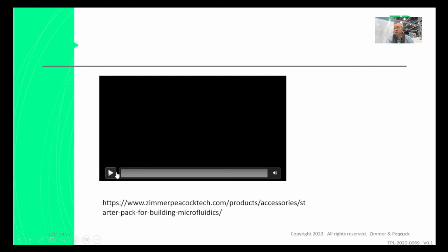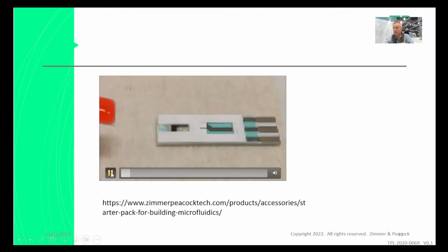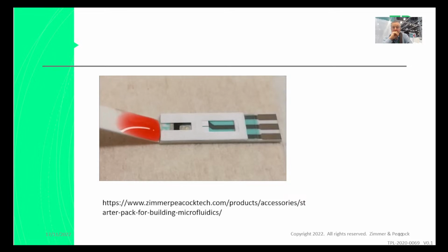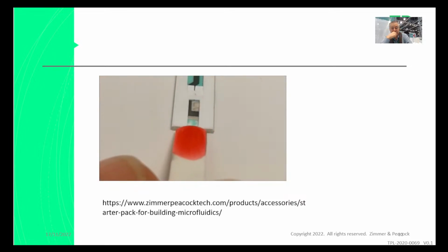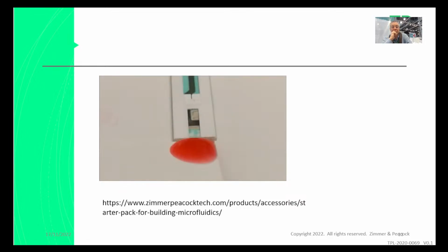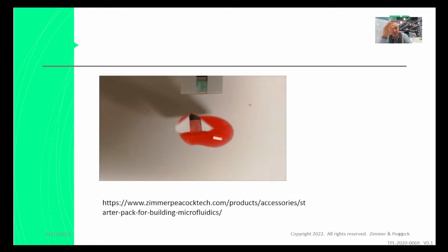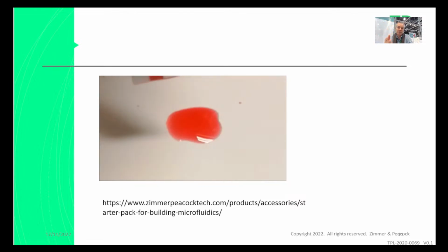Now that means you can construct devices like this. So you're not just pipetting the sample onto the sensors or electrodes, you're actually able to capillary fill the sample. You might notice there's something called an air hole. I'm reading the email from the inquirer, and they understand that you need this air hole, because otherwise these capillaries won't fill, because the air has nowhere to escape.